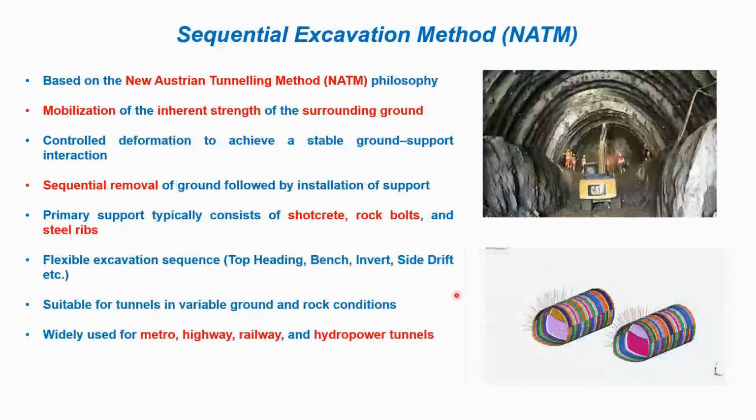The next one is the sequential excavation method, or the New Austrian Tunneling Method. This tunneling method is based on the concept that the surrounding ground itself should be treated as a structural component of the support system. It means we are relying on the mobilization of the inherent strength of the surrounding ground as well, apart from the other kinds of support system.